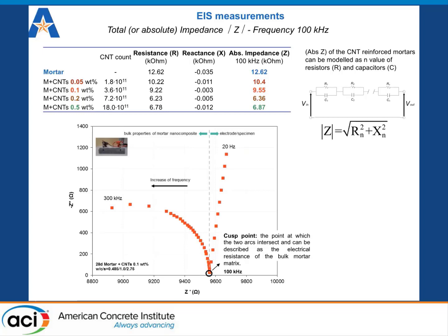We take two pieces of information: the real part of the impedance, known as resistance, which arises from the intrinsic resistance of nanotubes and depends on the development of a complete nanotube network within the matrix. And it is usually used to determine the critical amount of CNTs required for the formation of a continuous conductive network and providing information on the percolation threshold.